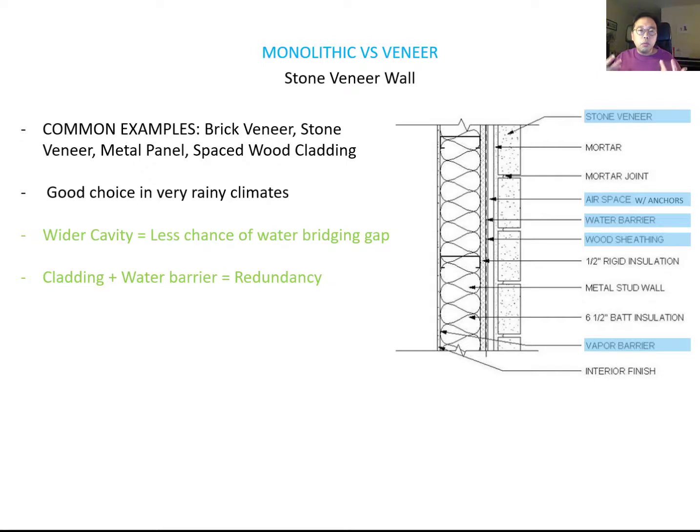You remember what a barrier wall is? It uses the rain screen system. We already discussed the rain screen system in the first or second lecture, which was the brick barrier system, but I will cover it one more time. What is your consideration in designing this barrier system and rain screen system? First of all, you need to add the structural wall framing, which uses metal studs. To hide the metal studs, you add the interior gypsum board. And to protect this framing, you add cover board here, which is the sheathing, right?